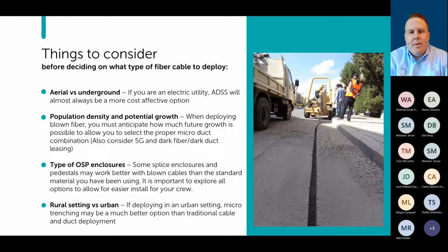Another area where this might be beneficial is if you're in a high-end neighborhood and the people there don't want boring machines in their yard. They definitely don't want trench machines in their yard, right? There are limitations there that maybe you can't get around. This can provide a much better option and still a very cost-effective way to get that duct in the ground. So again, the cable is going to go in the same way. It's just about how we're going to go about doing the duct.